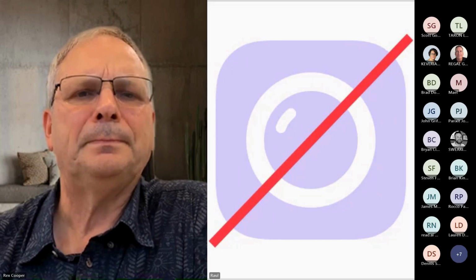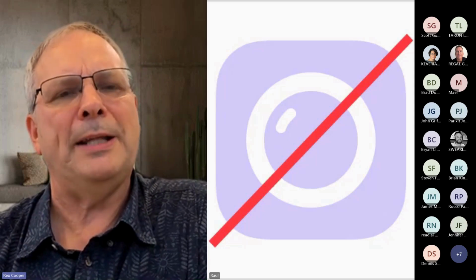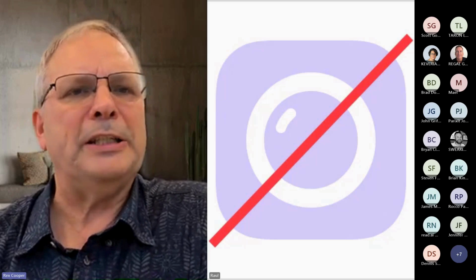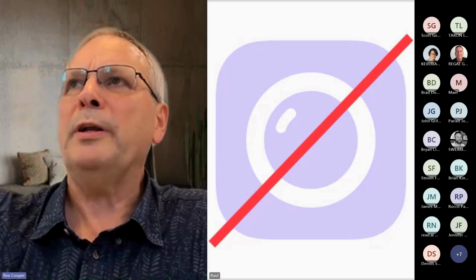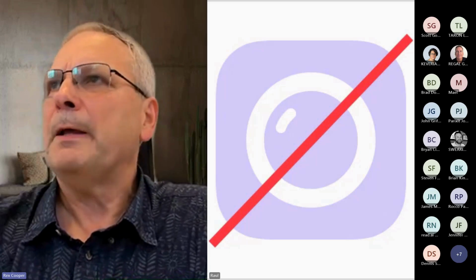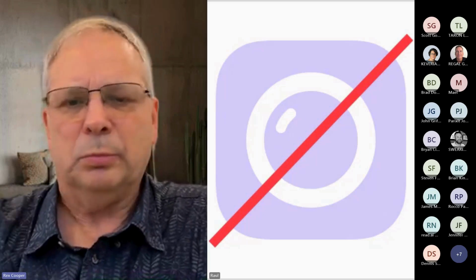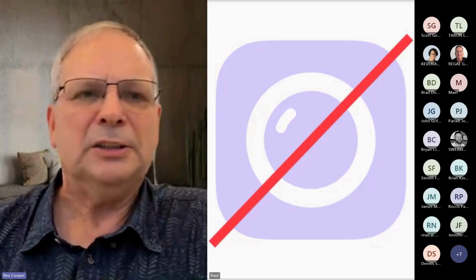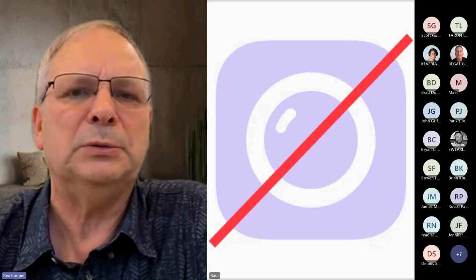Excellent. And like I said, in that short period of time, I got to show 18 of our little commands of 300 that are in the survey module. And we have other ones like Brad just mentioned, where you can interpolate a distance or pick a point and say, oh, I've got to go up a 1 foot slope and I've got to pick a point over here somewhere. Maybe I'm doing some subgrades or subdrains, and I want to do a 1% subdrain. What's the elevation going to be over there or over there? You start doing a bunch of what ifs, and it can do those calculations and place a label and or a point depending on what you want it to place.